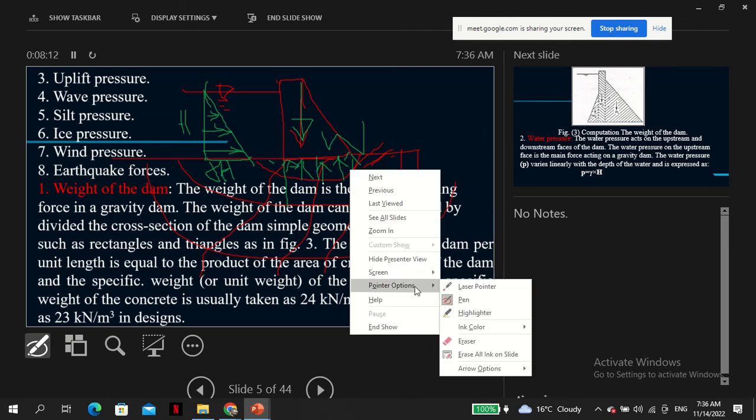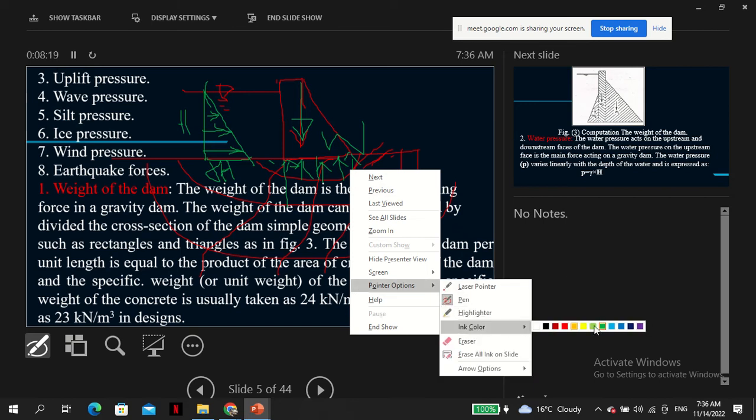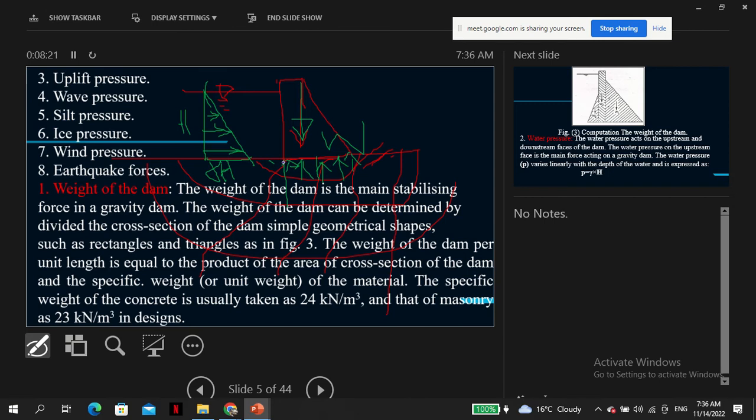Okay, let me use a different pen. If you don't remember this, please refer to your notes. You can calculate the head there, and the head somewhere there, and then you find some nice distribution, in which the salient values are known. Then you know the length of the dam, and finding the area of this pressure diagram would give the uplift force, you remember.